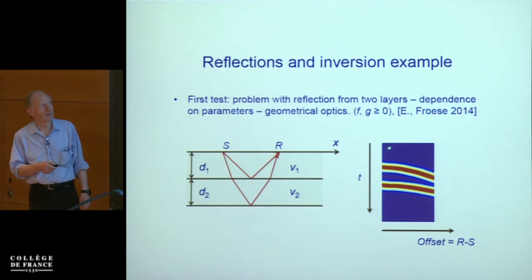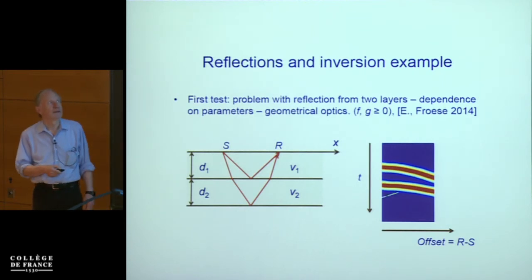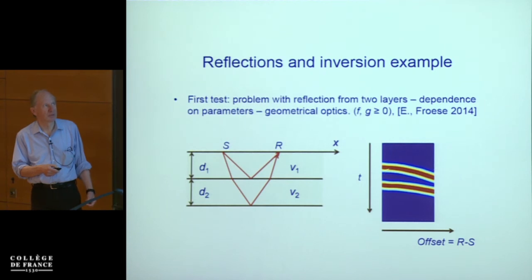So if they're on top of each other, you get a reflection that comes earlier in time than if you have this distance larger over here, when S and R is larger. So this is typically what it looked like. This would be the reflection in the first interface, and in the second. And then you have to play around with these variables in order to adjust them so that your measured data would be the same as the computed data that are based on these.